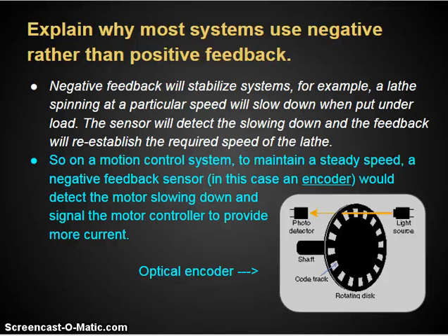An encoder, this is basically what an optical encoder looks like, this diagram. This is one type of an optical encoder. There's actually many of these. There's a disc that has holes or markings on it, and then there's a light source and a photodetector. The light source provides a source of light, and then the photodetector receives it. If it's got holes in it, like a simple disc like this, then every time the wheel is rotating, a pulse of light goes through and hits the optical encoder, and those pulses can be counted and calculated.